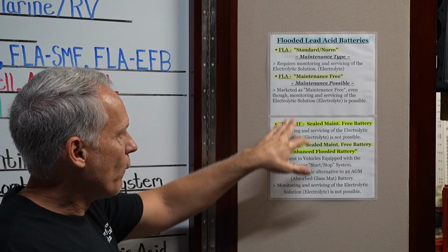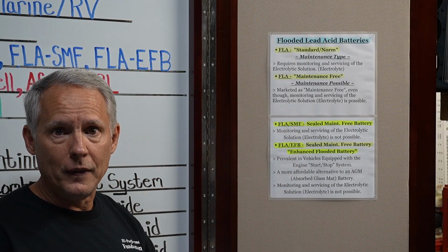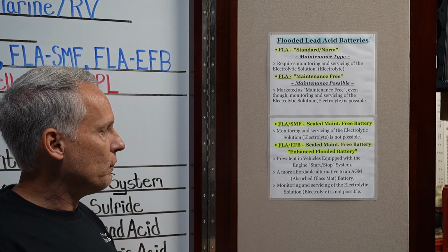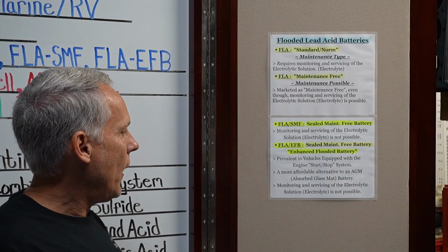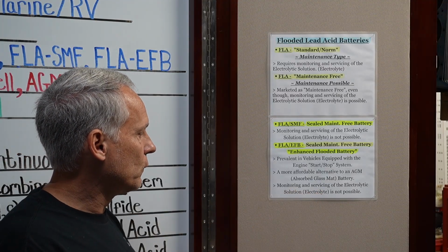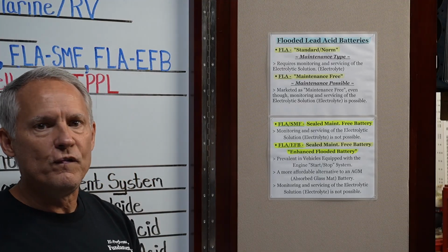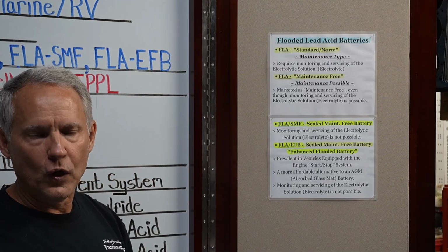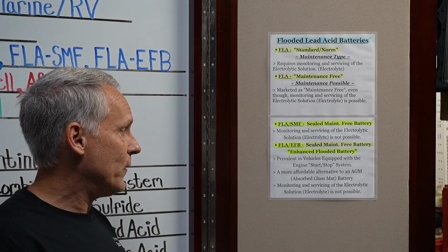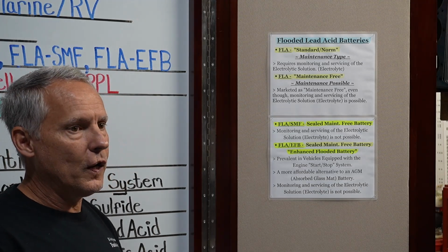The EFB tends to be more expensive than your standard liquid lead-acid battery, and they're a little cheaper than an absorbed glass mat battery. And monitoring and servicing of the electrolytic solution or electrolyte is not possible. Right? It is an open vent system battery, but it is sealed. It's not designed to be opened up. And like I mentioned, you could get in there and service it.